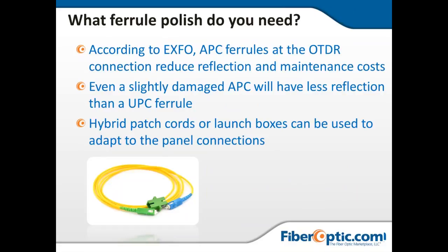Make sure that you're looking at those bandwidths and understanding them if you want to do live monitoring of fibers that you're up. If you're doing DWDM, I really recommend you bump up to the 1650. Even though you get a little less loss performance, because you start to tick up, it's still relatively effective measurement, and you can still get pretty good distance, but you also get a pretty nice separation between the other wavelengths that we're operating under.